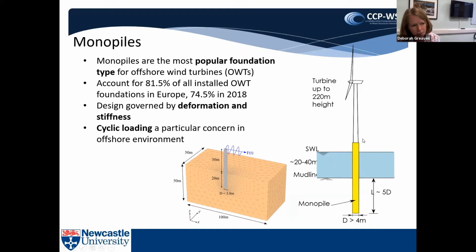But what happens there, and the vibrations that are fed through the monopile, will also have a significant effect on the foundation and the soil structure interaction under the ground. So coupling together the structural response with the soil structure interaction and the fluid loading is of interest there.